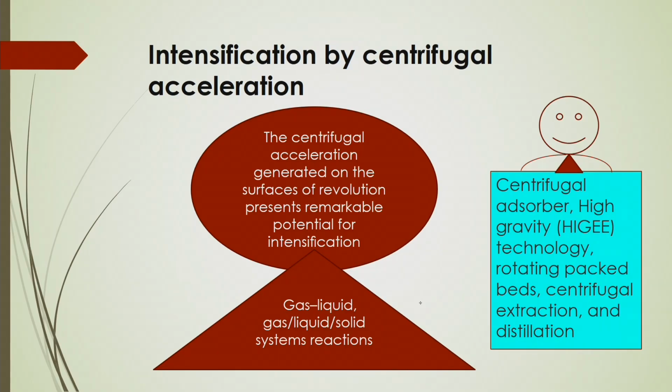In that case, by centrifugal acceleration you can also handle multi-phase reactions, gas liquid solid system reactors, whereas plug flow systems are one dimensional systems, and it is very difficult to handle multi-phase processes there, while centrifugal acceleration systems make it possible in both 2 and 3 phase systems.